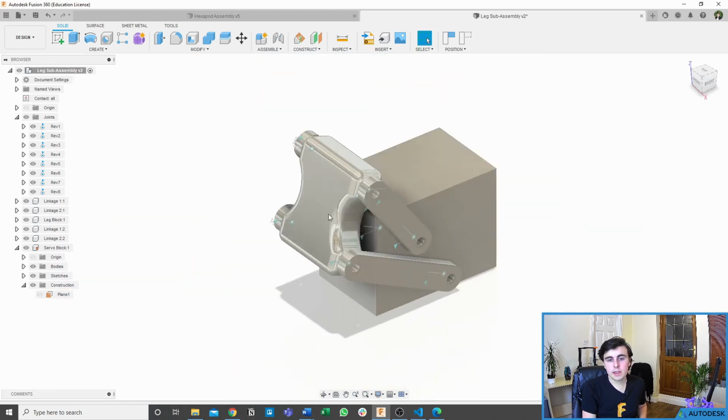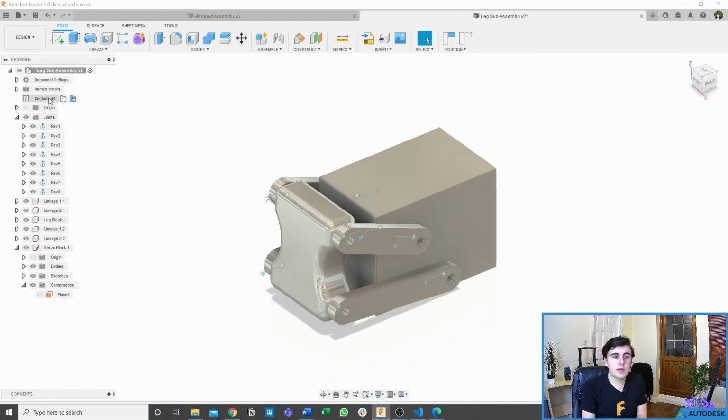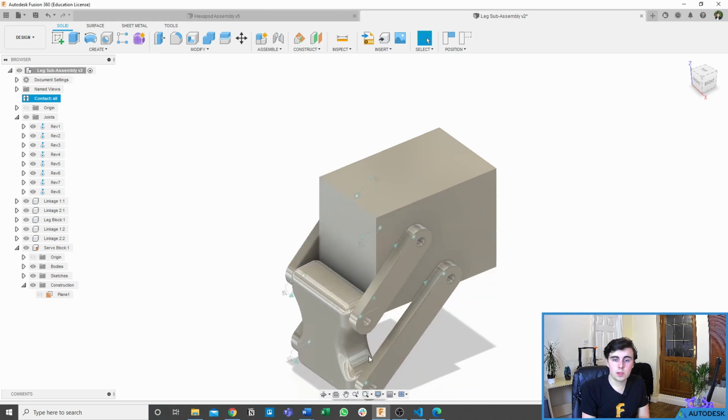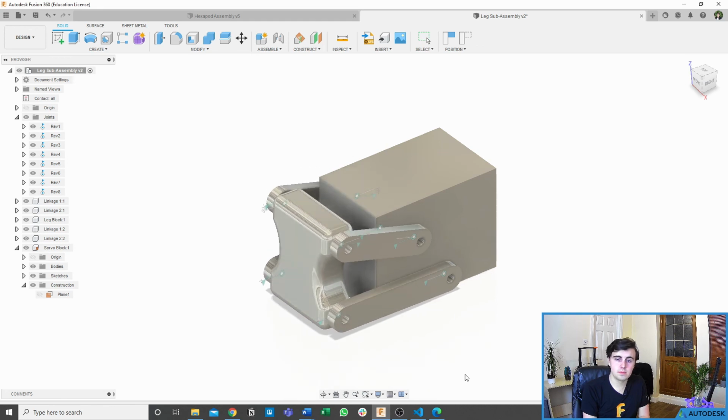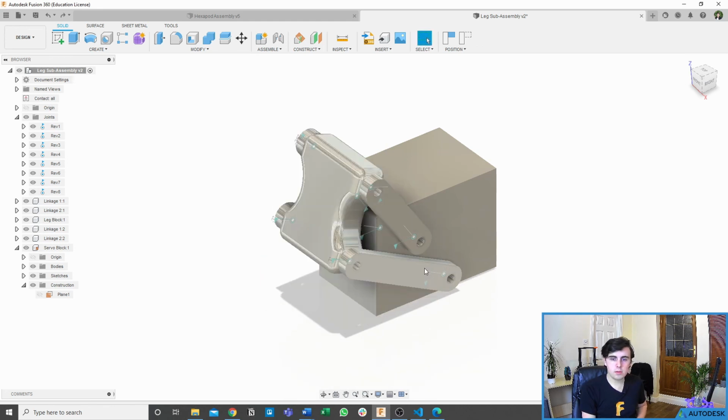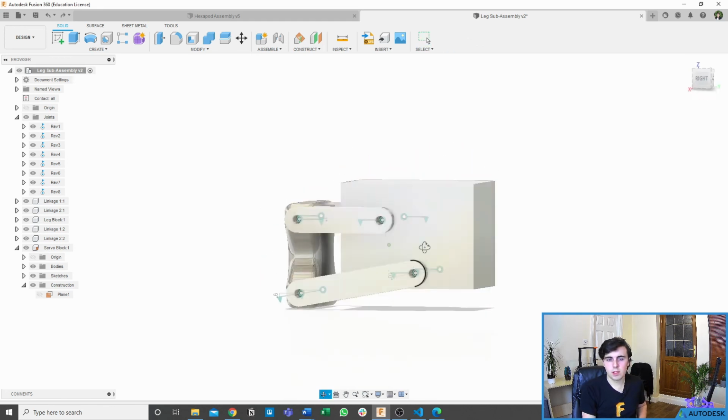There's therefore contact between these bodies. You can specifically add in contacts between specific bodies and not other ones, but in this case we're just going to enable all contact across this file. You'll see it also works at the bottom, so if we try and go below that part, it won't happen. I'm just going to undo, so our part's back in a nice regular place.